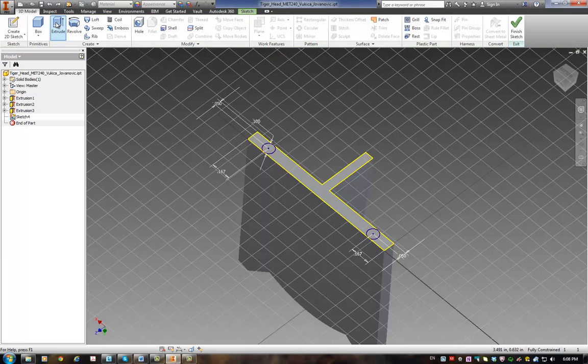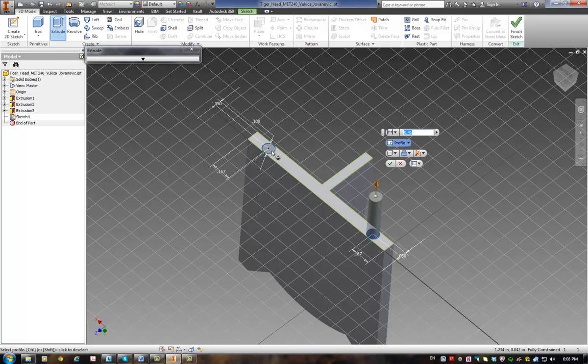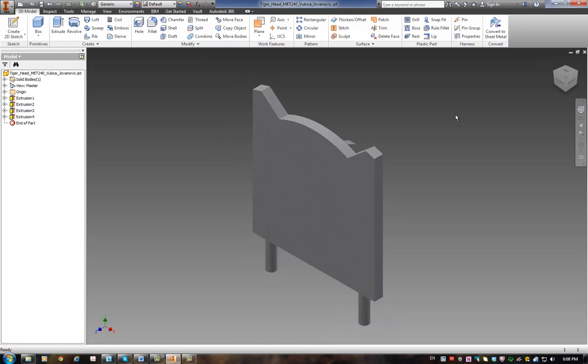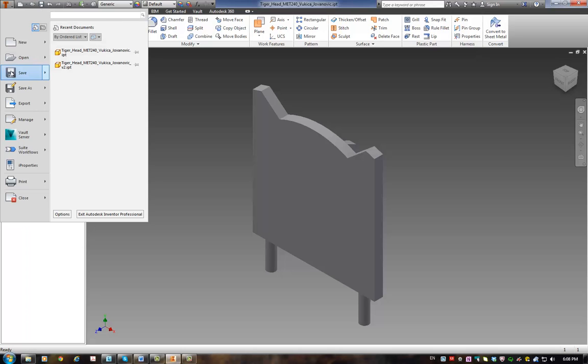3D model, extrude. Be a little bit more careful that I'm selecting inside and here. You can always zoom in. And then this would be 0.32, enter. Let me just check in the book if that's the right dimension. It is, okay. And now I'm done with my tiger, and I can always use here home to position the tiger face. And again, I can use save here or Control S, or I can go here, save.